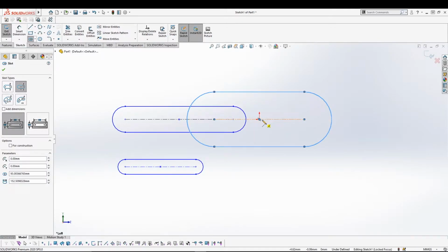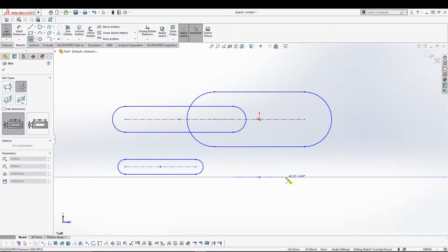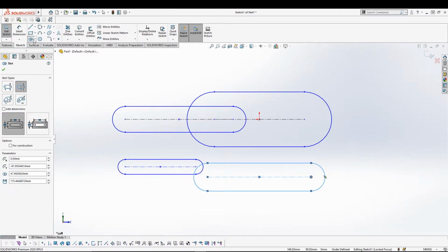Now this center point means the first point will be basically the midpoint of your slot. So the second point defines the length of the slot and third point will define the width of the slot, like this. First point, and if right now I'm giving my second point, you will see that it's extending to both the directions, the third point, like that.